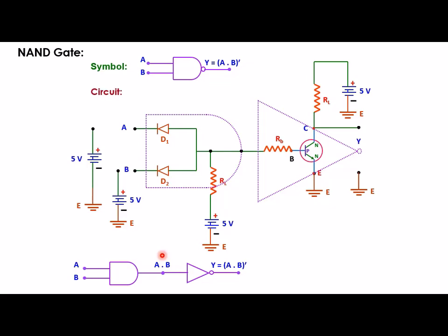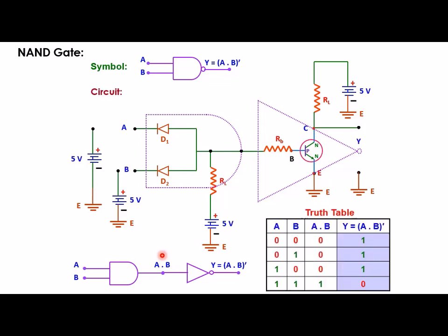If we try to write the truth table for this, the 4 different combinations of A and B are 00, 01, 10, 11, and the output of these two inputs at this point will be 0, 0, 0 and 1. That means this is the AND gate, which shows that only when both of the inputs are 1, the output will be equal to 1, and in all other cases the output will be equal to 0.